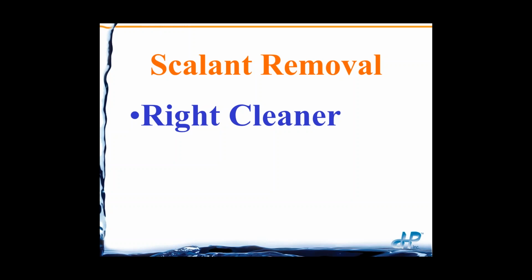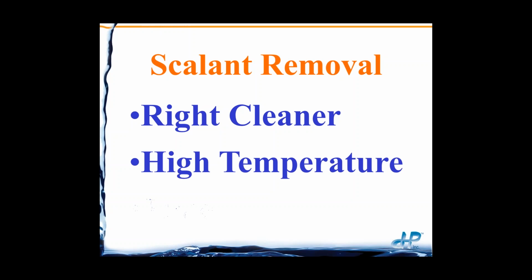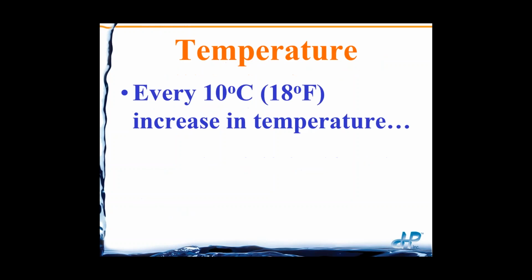We have to clean at an early enough stage to where we can make sure that we can get the cleaning solution to go in, and then the right cleaner, and then a high temperature, and then it's just going to take time. How long is it going to take to dissolve all of this scalant off of the membrane?